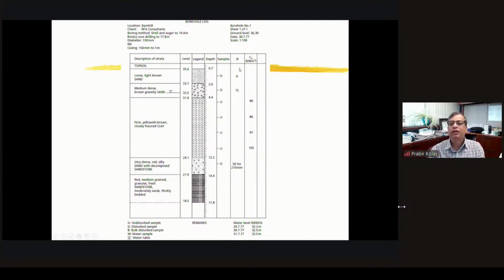Okay. And then also, as I mentioned earlier, the SPT N value. So if the N value is more, obviously, the soil is strong, right? And then also unconfined compressive strength should sometimes be mentioned. It depends on what type of project. And then depending on that, people make a borehole and then log this data. So most of the time, people use SPT value.